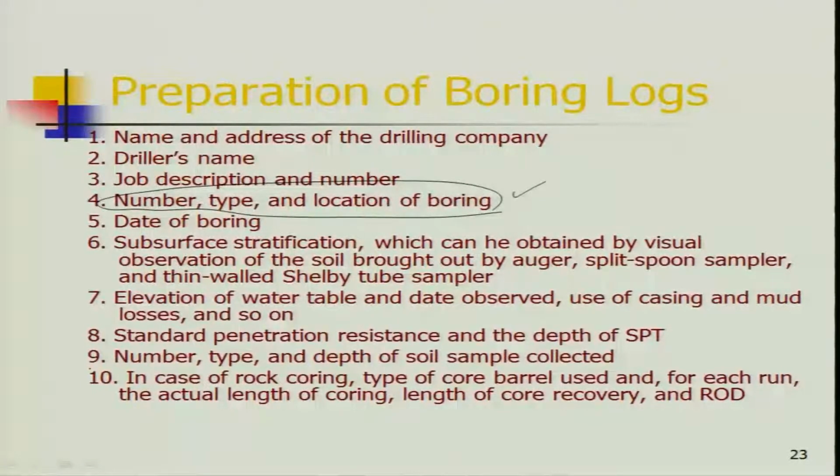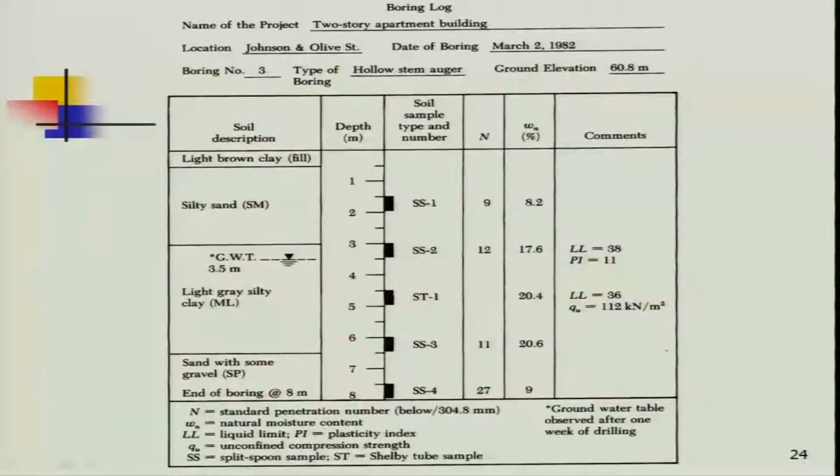Standard penetration resistance and depth of SPT, and the number, type and depth of the soil samples collected, are also important. I have explained this. In case of rock coring, record the type of core barrel used and, for each run, the actual length of coring and the length of core recovered. Keep all this data in mind before preparing the log.